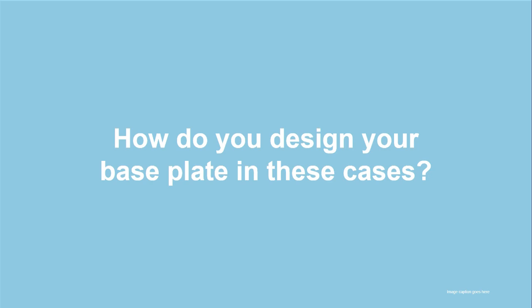But how do you then design the stiffeners? Take the thickness of the web of the member, just make it either the same or larger. Yeah, but if it's, again, a 36, and you need to make it larger, that's then again, I think, an experience point, or I would call it good engineering practice. It's a first step. I think it's good, but still, we believe that there are quite some things you can do better there. And also, then designing the weld, because you will need to weld the stiffener to the profile, and you will also need to weld the stiffener to the plate, right? So there is quite some stuff that is needed.